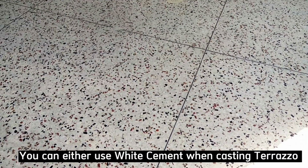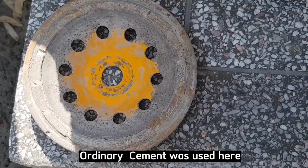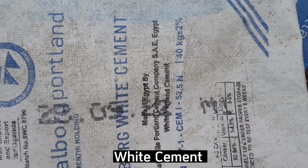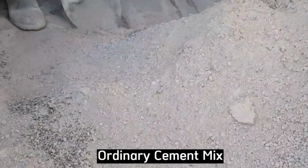You can clearly tell even in a finished floor that this was either white cement used or ordinary cement, because a floor where white cement was used glitters, whereas ordinary cement is dull in color. Use either ordinary cement or white cement depending on the work that you are going to do. If we are focusing on strength or taking strength as priority, use ordinary cement.